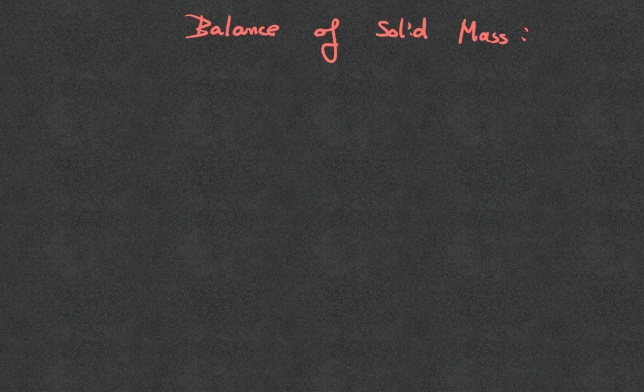By the way, when we look at the porous media literature, there is also another way of dividing the balance of mass. In what we show here in the course, we always develop the balance of mass for each individual phase, and then we add them together to cancel out the terms. But then there's another way, like Jim Rice or John Vardoulakis, they simply have the balance of fluid mass, and they don't consider the solid. Okay, and that is also okay, because either way, it gives you enough constraints to write the balance law. You should get the same results if you write it correctly. Okay.